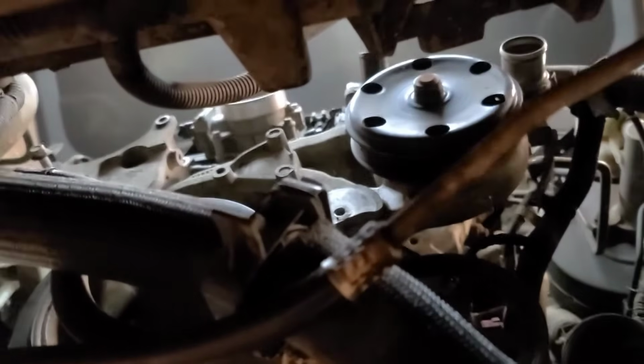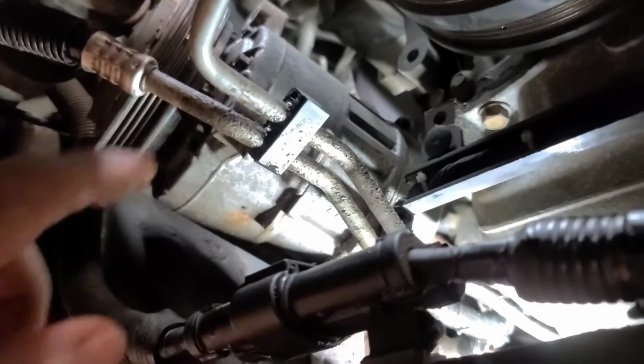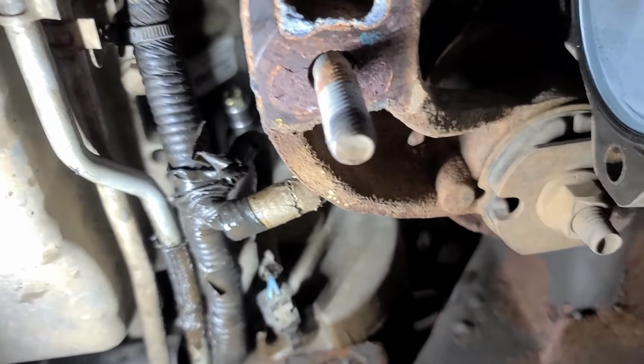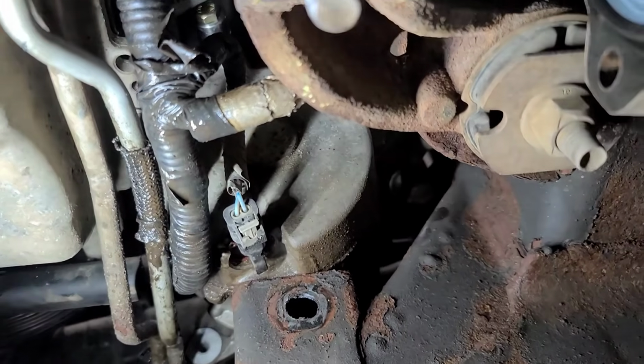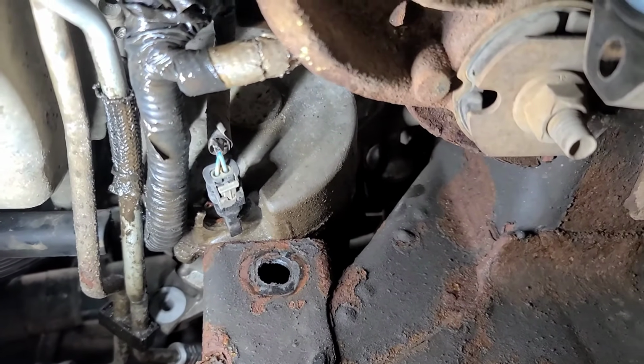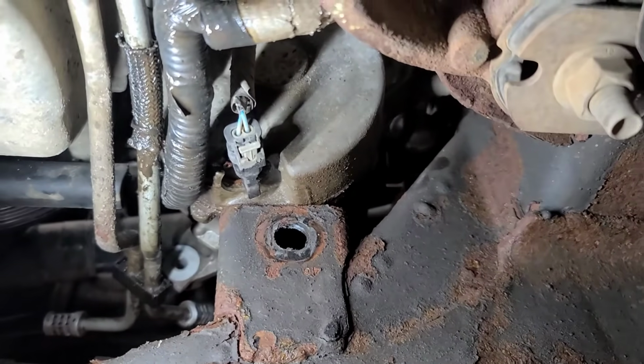So I got the water pump back on, water pump housing. Water pump is serviced separate from that housing. Now the challenge is to get this AC compressor back up there, and it's got one of those sliding bushings at the back end of it. So I'm going to put a socket on it, like you can see here, to pull that bushing back this way slightly so that I don't have trouble getting the AC compressor back up. You only have to move it about 1 millimeter just to give you some slack.